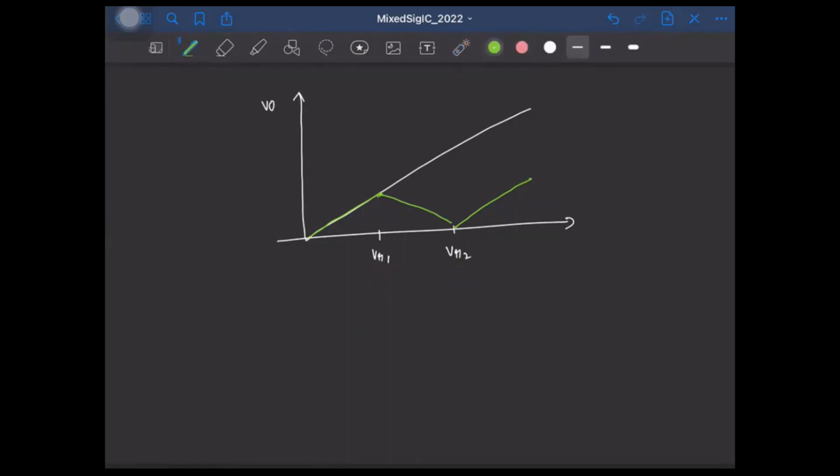And of course, you can have a combination of this folding technique as well as interpolation also. And again, this was popularly done in the olden times. In modern times, this has not gained a lot of traction because we have pipeline ADCs, which are much more efficient in improving the resolution without compromising the speed. Right? So we'll discuss pipeline ADCs in the future classes.